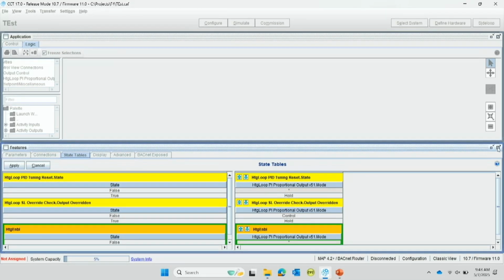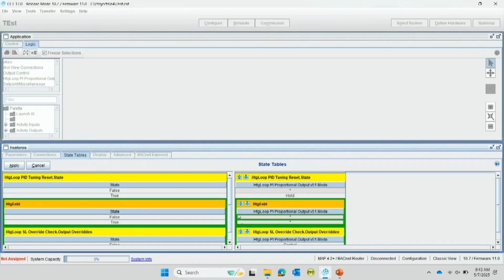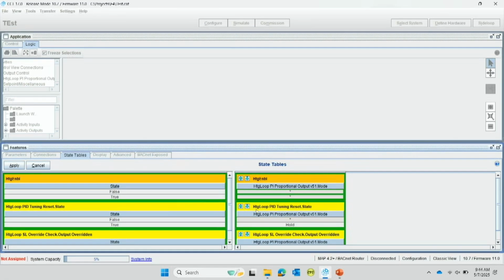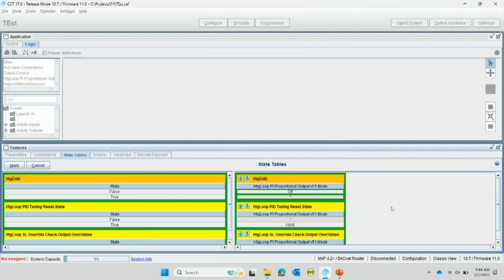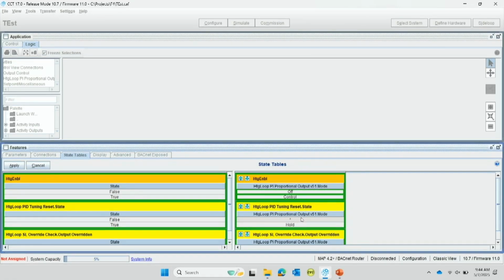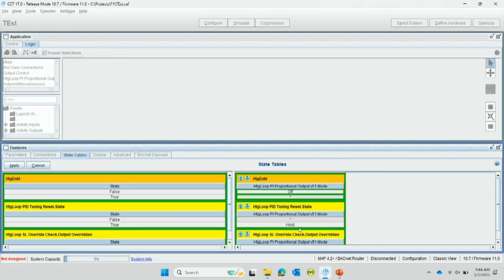Well, because it's a ball falling from the top, it's looking for the first priority. I wanted that to be heating enable. Oops, I put that at the bottom. No problem, I can use these arrows, just bump it up. So I say, okay, if heating is enabled, false, then shut that PID loop off. If heating is true, is enabled, I could say, go to control here, but then it'll never move past that point to cross-reference if we're in a tuning reset or if we're overridden, right? So if it's true, I'm just gonna say do nothing, look to the next thing.